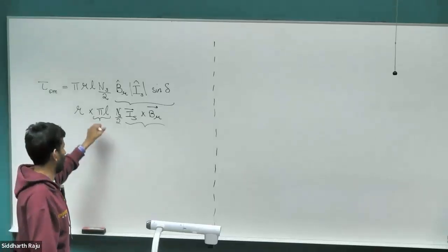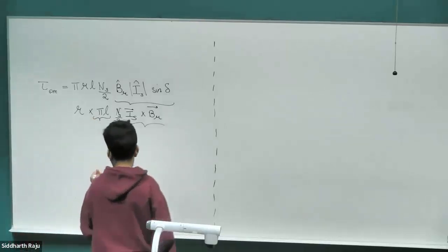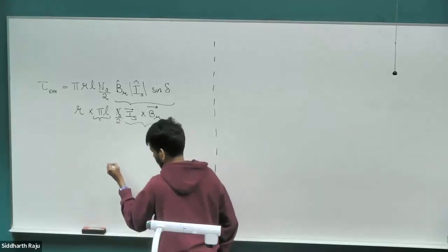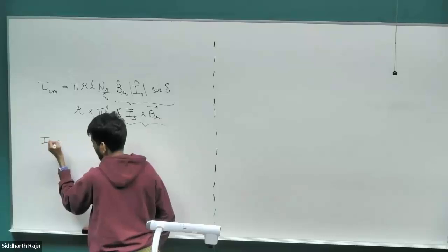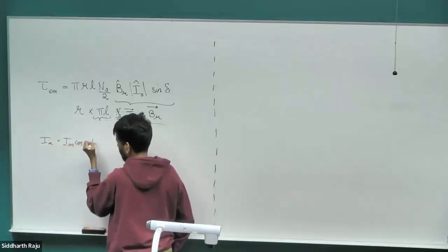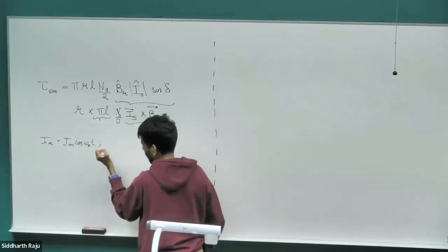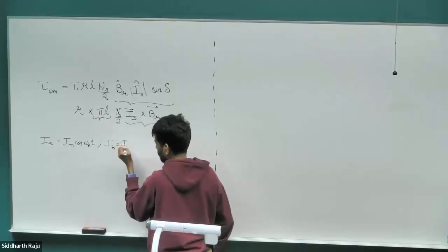So we have gotten something similar, but the pi factor comes from the sinusoidal distribution of our winding. And then we went ahead and drew the space vector for this. So let's say our currents are, let's give some values to it. IA is some Im magnitude, cos omega Et, where omega E is the electrical frequency, 2 pi times F, whatever the grid frequency is, if it's a grid connected motor.